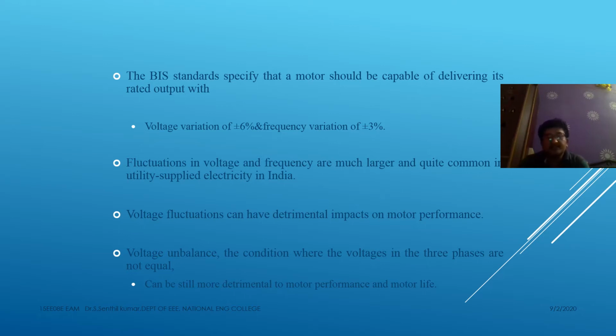And next, as we said before, voltage unbalance also affects the motor performance. It is the condition where the voltages in the 3 phases are not equal. If the 3 phases of the input supply are unbalanced, it is surely going to affect the motor performance and the motor life also.